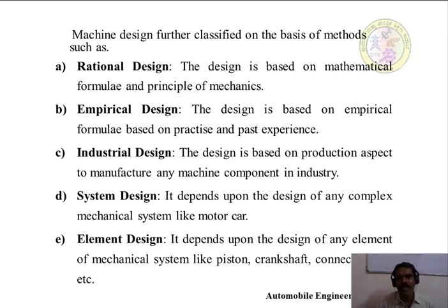So empirical design means the design is based on empirical formulae, based on practice or past experience. So what is an empirical formula? For example, while designing a shaft, for the length of the shaft you can take L is equal to 2D, L is equal to 3D, L is equal to 4D, like this. Such parameters, 2D, 3D, are called empirical formulae. Such a type of design is called empirical design.